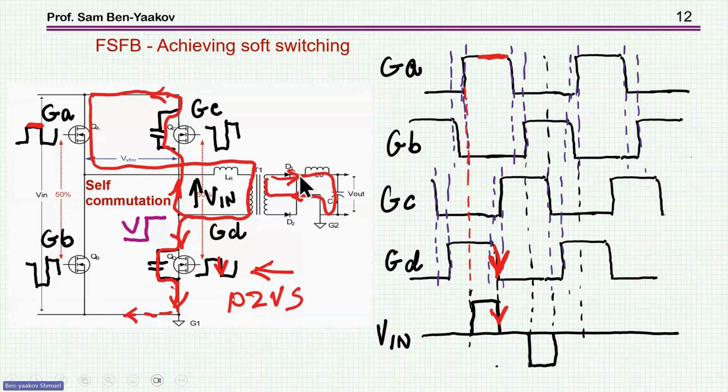The power should be high enough, so you have sufficient current to charge this capacitor. I'll talk about it a little bit later, because it has to do also with this inductor. But at this point also, it's important to understand that you can lose this pseudo voltage switching if there isn't enough current at the secondary, which is reflected to the primary and responsible for charging these capacitors.